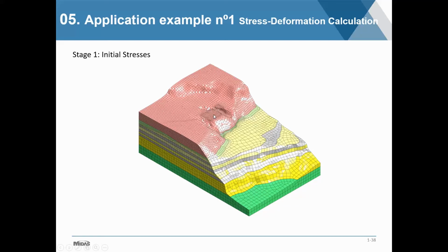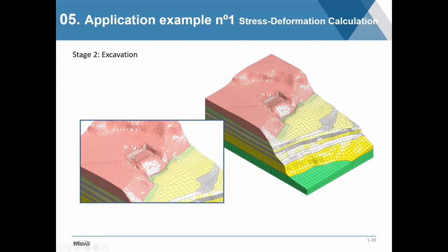in the same model, so long as they're not activated at the same time or in the same stages. In this case, we're going to follow a sequence of deactivating these mesh sets and then later activating other mesh in the same location that are now related to the bridge. This is possible in Midas, but this is not possible in Flac, and hence the mesh cannot be exported as it is. We'll see in a minute how we get around that problem.